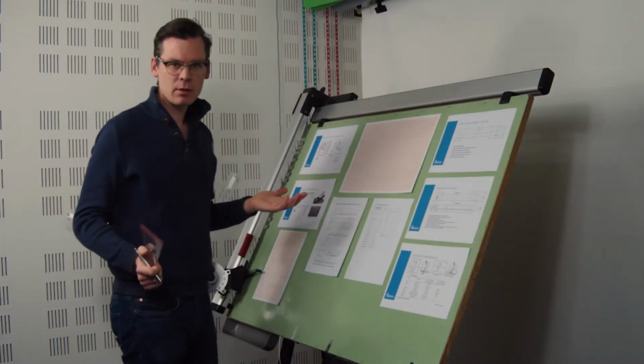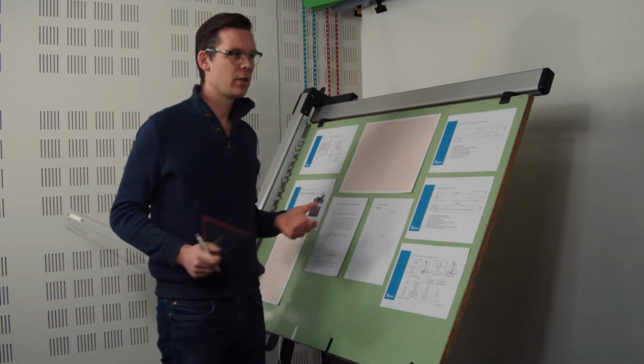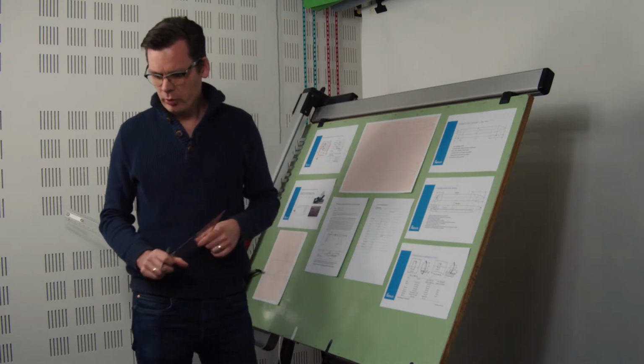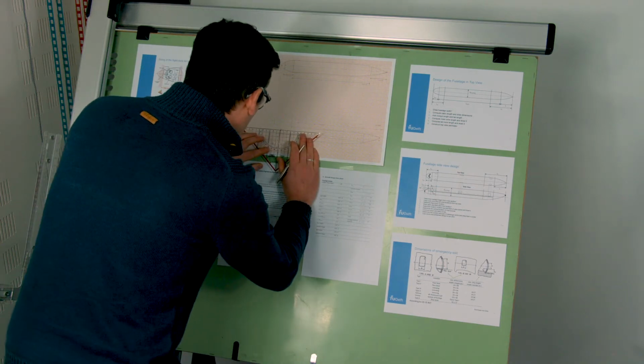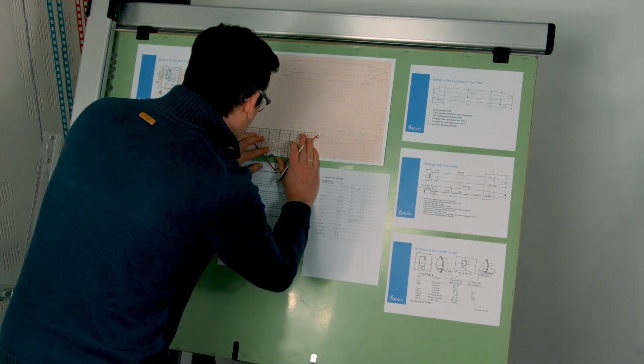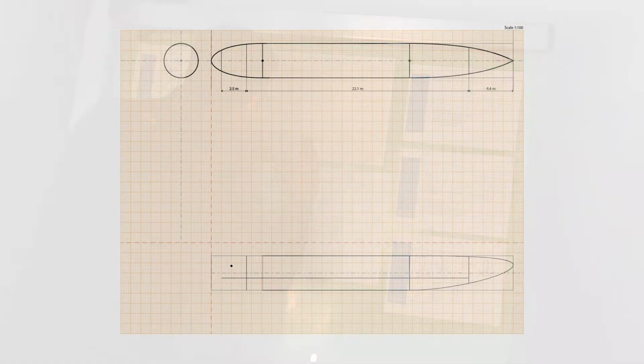Now I'm deciding that I want this pilot to have an over nose angle of 25 degrees. So he needs to be able to look down 25 degrees, and an upward viewing angle of 30 degrees. Those are quite common angles for this type of aircraft.